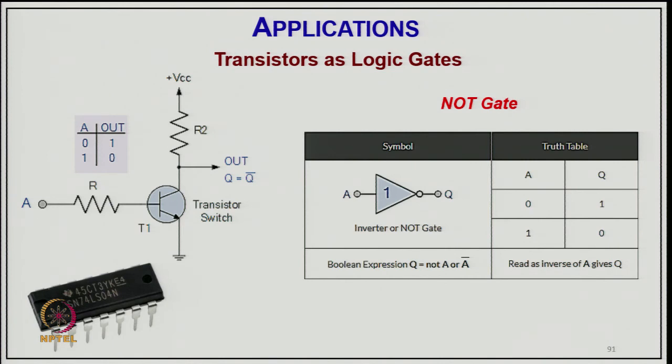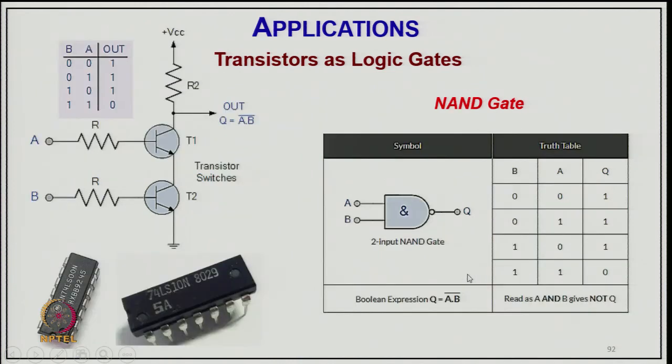And this is the third logic gate, the NOT gate. This is just an inverting amplifier; we already talked about the common emitter. You give a signal here, and when it is on, this will be grounded, so you get 0. When it is off, you get 1 here. We call this the NOT gate, and this is its logic table, the truth table of the NOT gate.